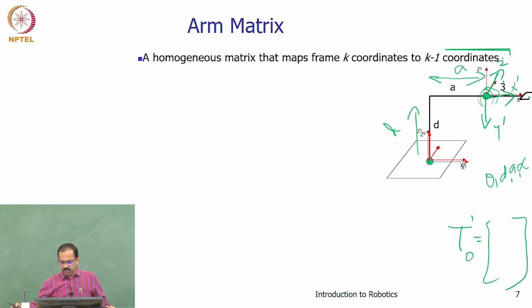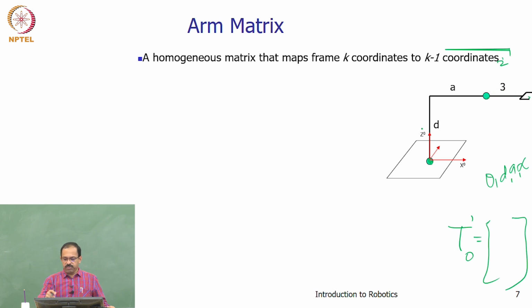So this is explained here. You have this z axis here, this coordinate frame here. Now, how is this coordinate frame coming to this coordinate frame? How can I describe the transformation of the coordinate frame? It translates along the z axis and then translates along the x axis, then it rotates, and then there is a theta rotation which I cannot show here.